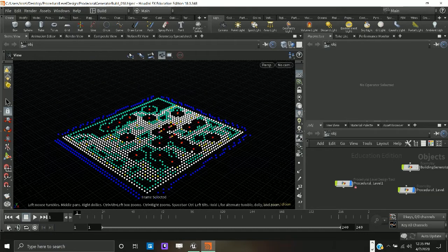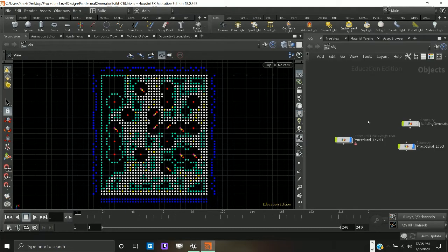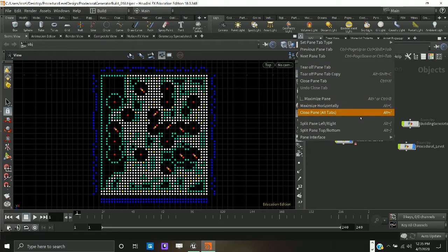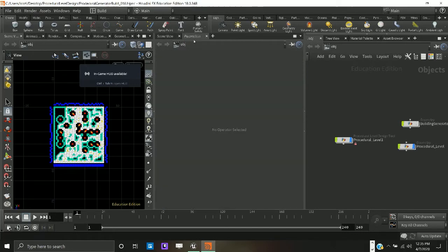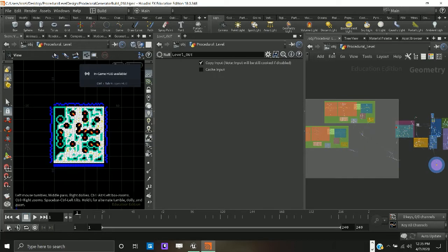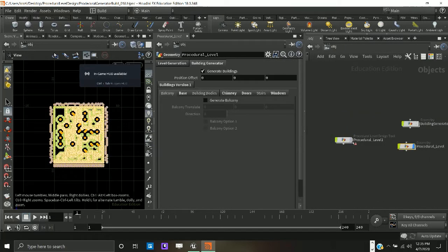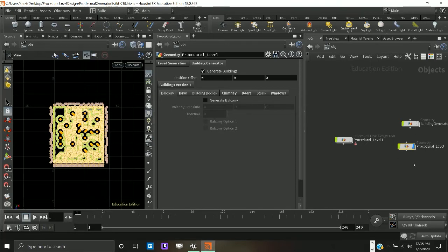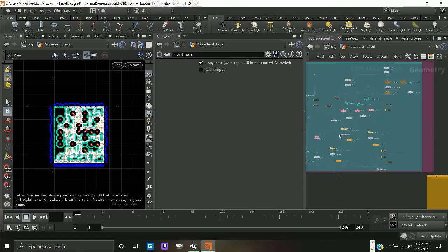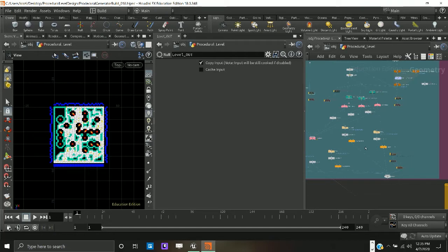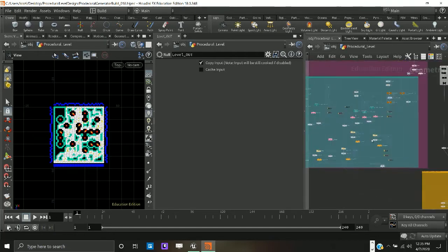Just to show you the node in here that actually is controlling the normals. Just so y'all know, this is the actual HDA. I just copy and pasted all this network of points to here, so that if I ever needed to go back and edit any of these guys, I can, without messing up the HDA or being able to put the HDA back out.